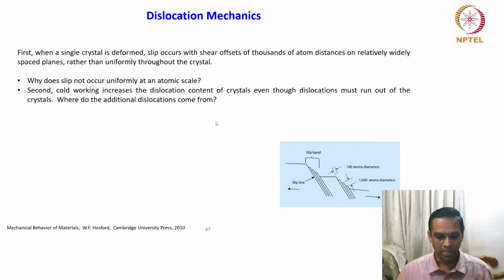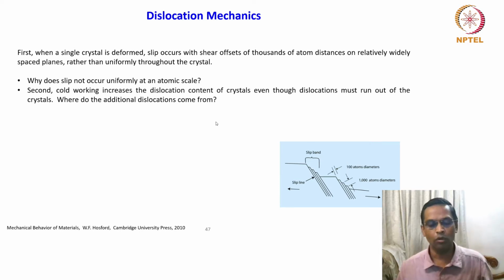You have to understand one important point. While these crystals undergo deformation, especially plastic deformation at room temperature, though the defect density increases, most of the defects run out of the crystal system. The velocity at which the dislocation moves is pretty fast. We will discuss that when we come to the deformation behavior.